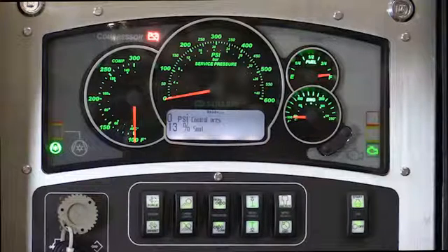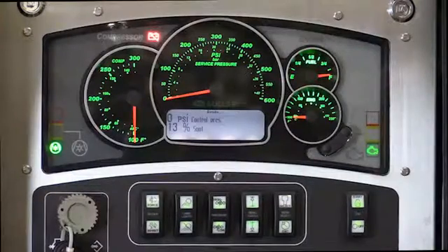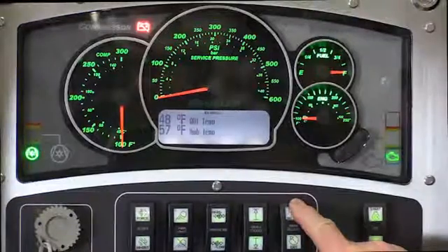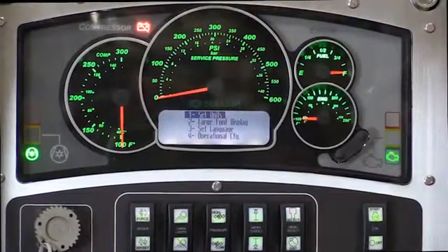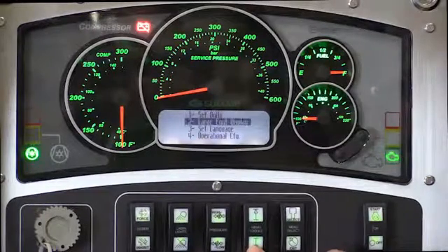Once the initialization sequence is complete and from the ready state, the operator can enter the settings and diagnostics menu by holding the select exit switch in the select position for 2 seconds. This will bring up the settings menu. The toggle switch is used to scroll up and down through the current menu list.